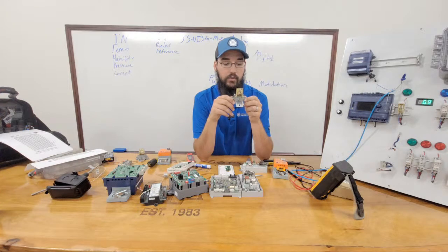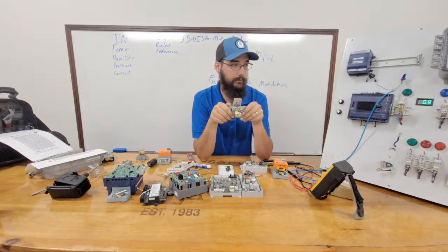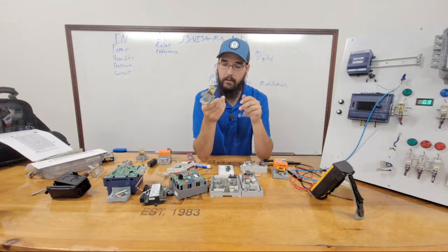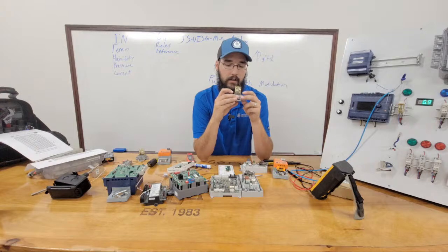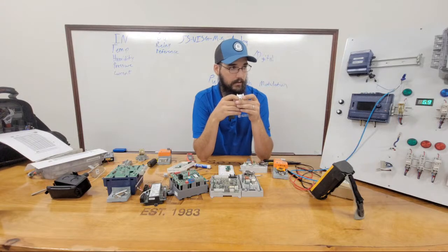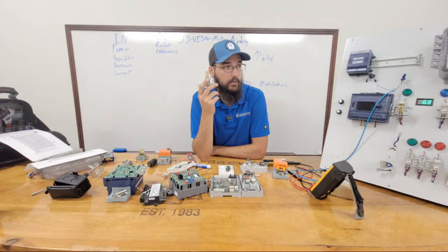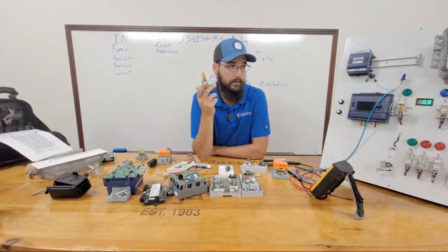And while that is true, it will do that amperage. In my experience, it won't do it for as long as you want it to. Okay? Typically we put something in like this, say it's running just a little small heater of some kind. Or even just a motor. Maybe you use this to operate your blower motor.